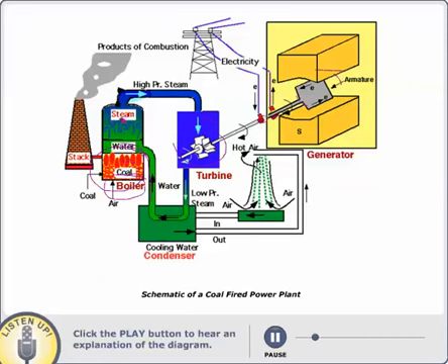This steam at high pressures and temperatures has a lot of energy, kinetic energy, and this energy basically comes into this turbine and turns this turbine's wheels. And we use this high pressure steam to do that. And this high pressure steam gives up the energy here and then turns into low pressure, low temperature steam. And this turbine is hooked up to a generator.